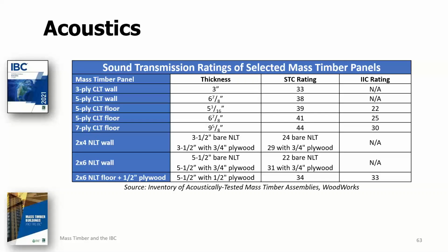This is one of the main acoustical design distinctions between light wood frame floor ceiling assemblies and mass timber floor ceiling assemblies. In light frame construction, acoustical components are typically included both above and within and even below the assembly. For example, you have underlayment and or concrete topping above the framing. You have batt insulation between the framing members, and then typically you'll have resilient channels and gypsum board ceiling under the framing. That's not always so for mass timber, and hence there are sometimes challenges for achieving the minimum required sound transmission classes.